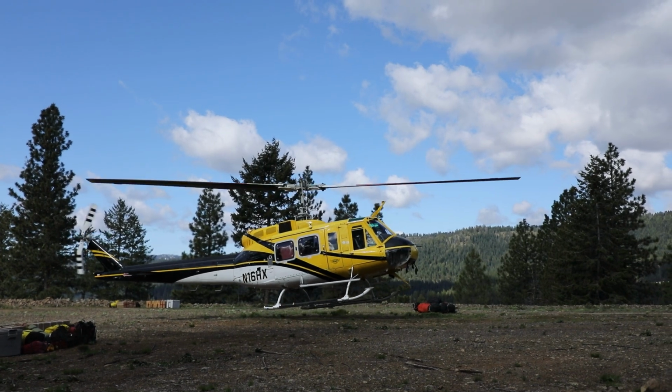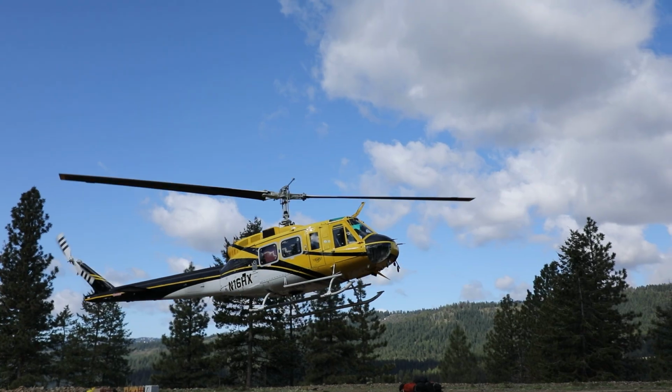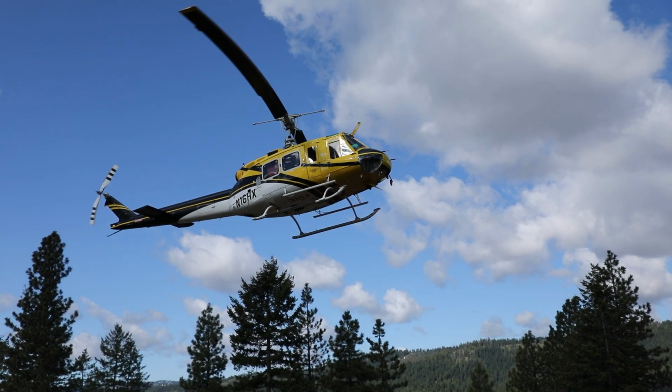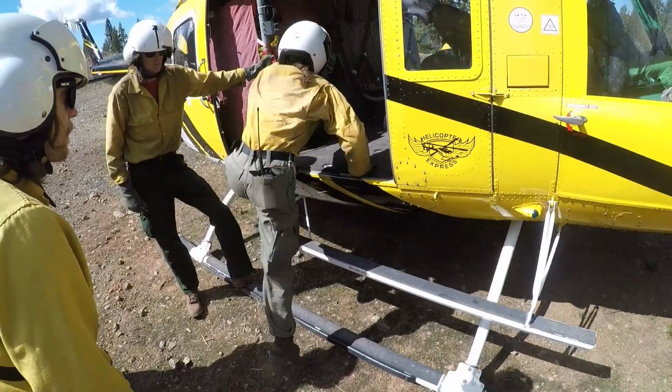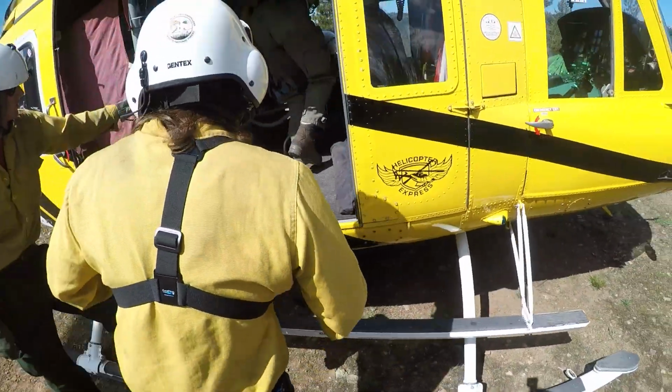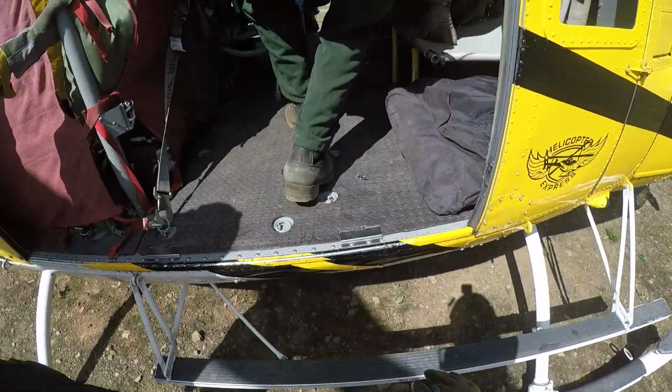The helicopter is much more efficient when it can use in-ground effect sites for takeoffs and landings. If you must use an out-of-ground effect site, the number of people or pounds of cargo you can carry may have to be reduced drastically.